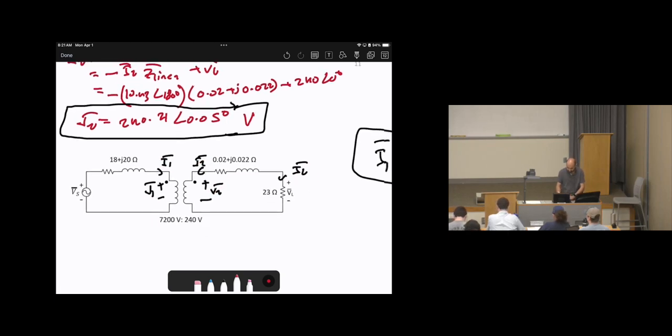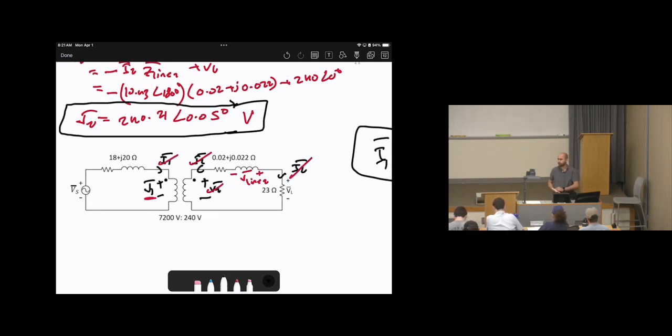So the voltage formula, again, how can I know I need to apply the voltage formula or I need to apply the current formula? You need to find the voltage formula. You need to find the current formula. And the same thing, whenever you see the transformer in the middle, you need to use one of the transformer formulas. Because V1 in one side, primary side, V2 in the secondary side, then definitely I need to use the transformer formulas. And the same when I say I1 in the primary side, I2 in the secondary side, then definitely I need to use the transformer formulas.